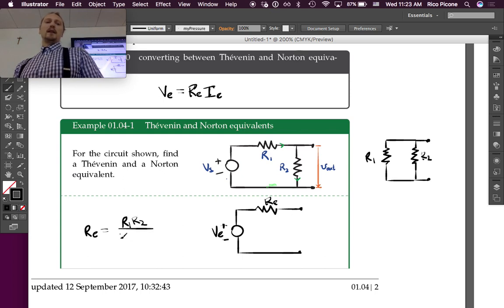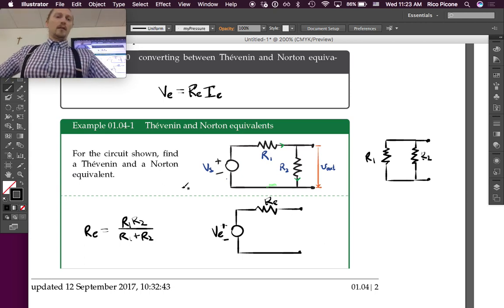So this is the sort of shortcut formula, right? But 1 over R1 plus 1 over R2 is the formula for resistors in parallel. In series, they would have been added, but since they're in parallel, they are combined this way. Okay, that's not too bad.